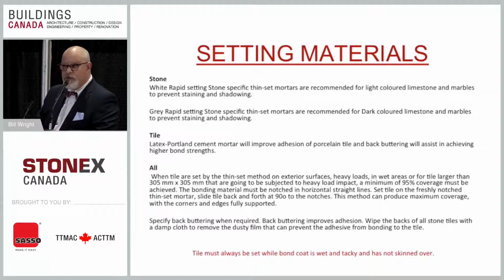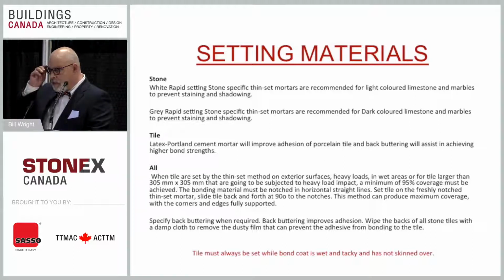So it's really important that we use the proper setting materials for the proper use. And mortar manufacturers have gotten very, very smart. Years ago there was one option, and now there are literally hundreds of different types of mortars for different applications, from glass to stone to tile to large format tile. Get the input of either the specifier, the product you're using, or the individual mortar manufacturers as to what's best to use. We want, like I said, fast setting mortars for stone.